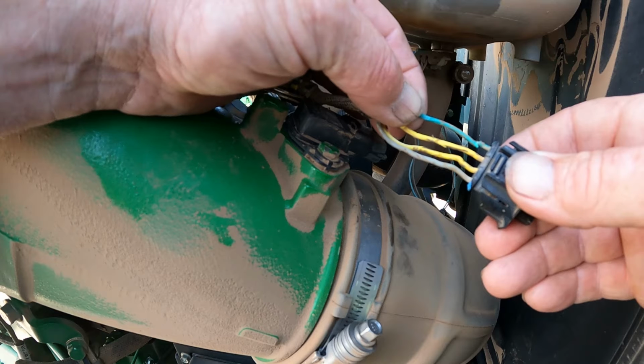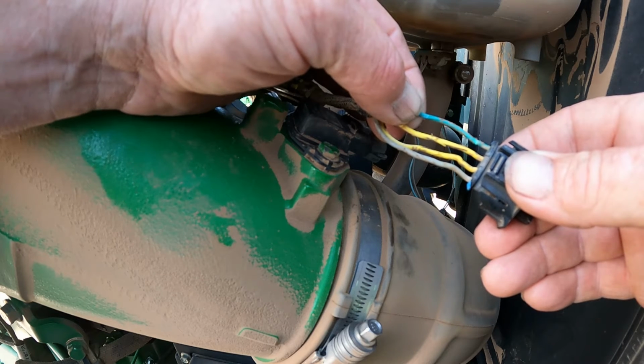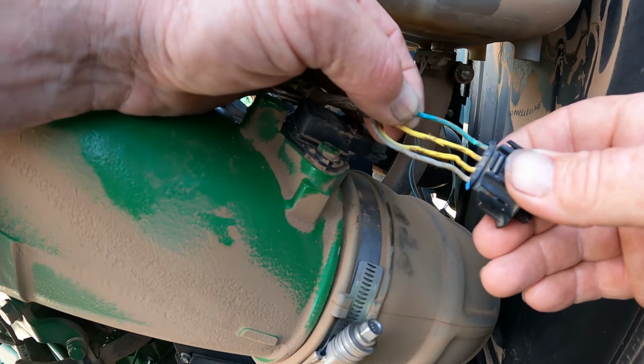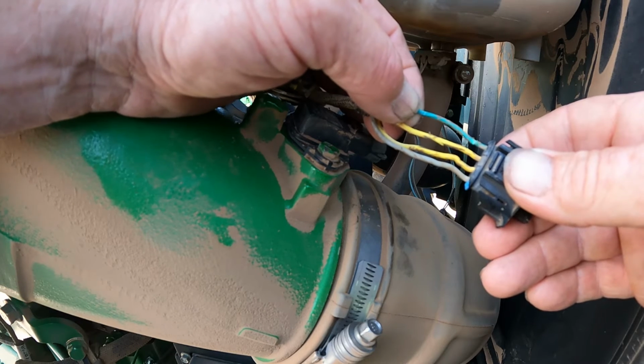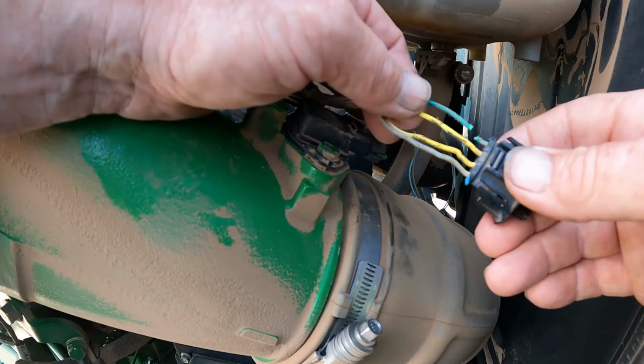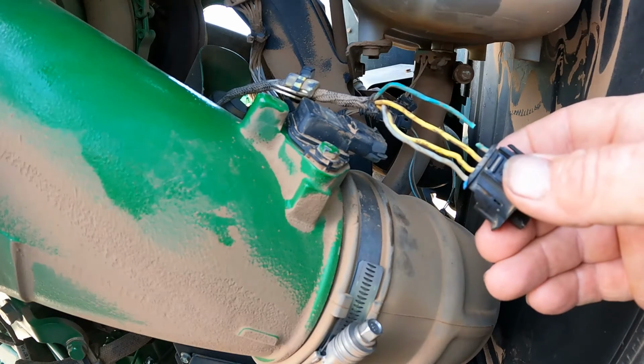So the plastic coating was still in contact there, or together, and basically making an intermittent connection, okay? So you would probably find that if you've done a current load test on the wire and went through the diagnostics, but just a quick reference, I just inspected that and found that problem right away.